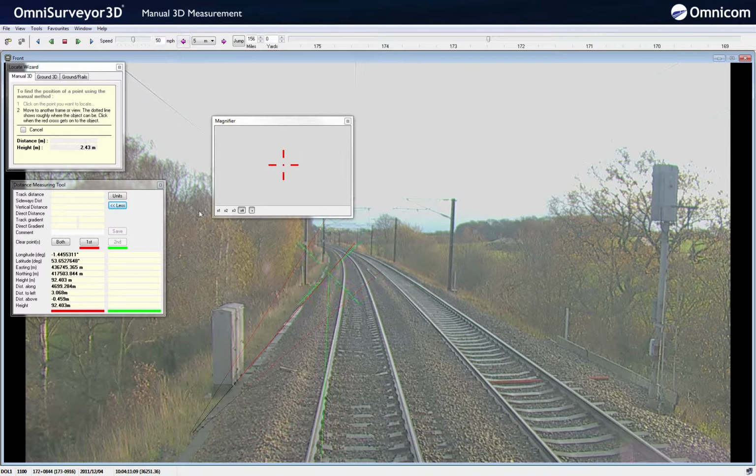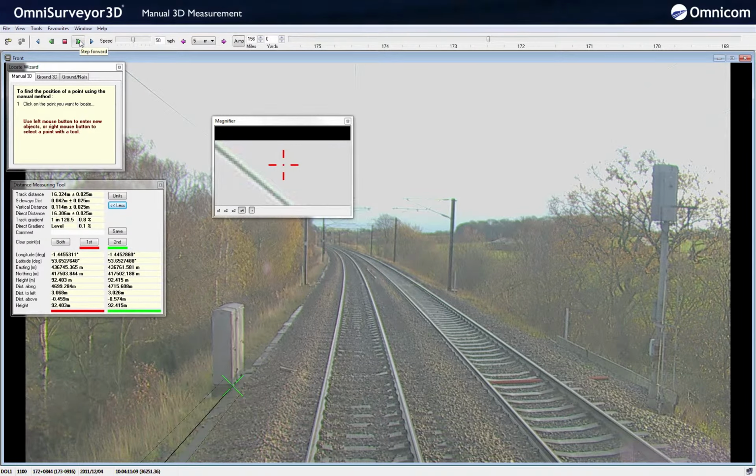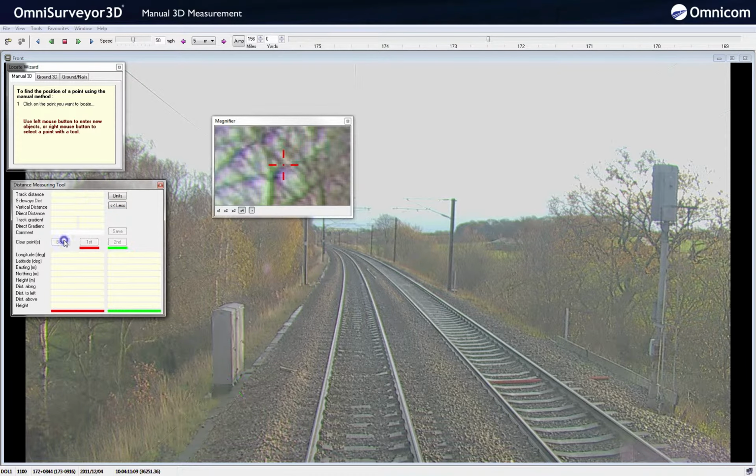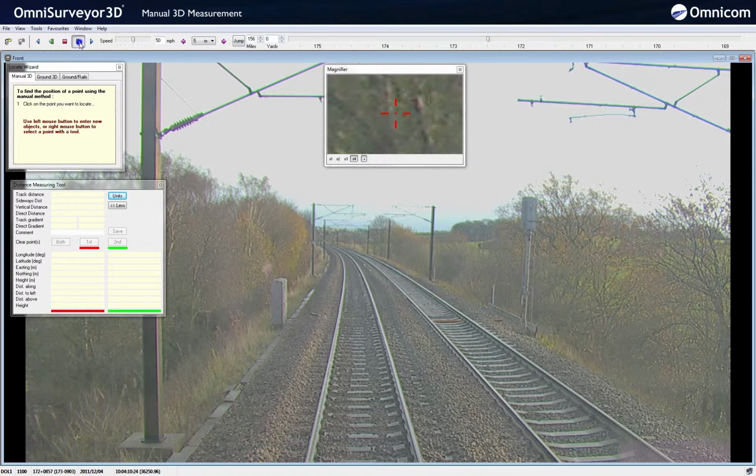Jump back 5 meters and pick the same point again by right-clicking. Check for any float. The Distance Measuring tool window will now be populated with the various measurements, along with the positional information for both of the pixels picked. A true directionally horizontal or vertical measurement can be obtained by following the same procedure for picking the first pixel, and then holding down the Shift key prior to picking the second pixel.